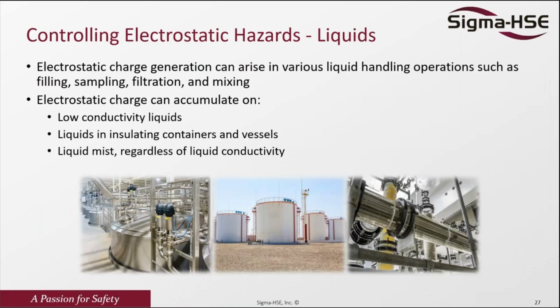So how about controlling electrostatic hazard for liquid? Electrostatic charge generation can arise in various liquid handling operations, such as filling, sampling, filtration, and mixing. That is something very, very common in the industry. Depending on the conductivity of the materials, it can create a significant amount of charge that could discharge. Normally, if you have a low conductive liquid, or a liquid in an insulated container or vessel, even though the liquid could be conductive, if the liquid is stored or being transferred into an insulated container, it's still the same problem.